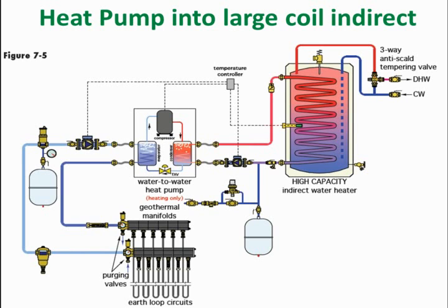What else on that? I think everything else we've talked about on that. Again, a little boiler trim package, expansion tank on the side here, temperature control. That's what's driving this system here: the temperature control, reading the temperature of the tank. Again, the geo heat pump is looking at the tank as its target that it's shooting to maintain, by the sensor mounted in the center port of that tank.